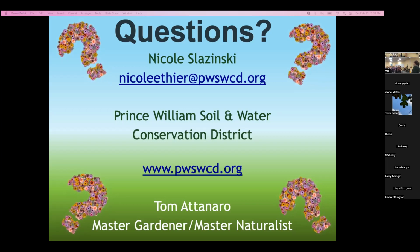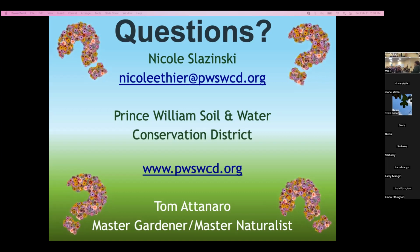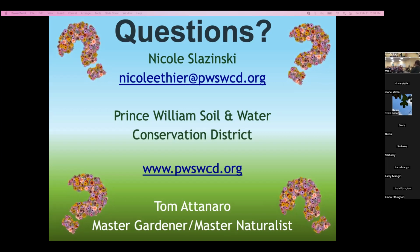Yeah, possibly. I would do the infiltration test first, because if it passes the infiltration test, you can do a rain garden. If it's really wet, there's other practices that I didn't get into, like installing a dry well, which basically will temporarily hold all that water and then let it slowly recharge the groundwater. We haven't done any of those yet, but there's definitely other options.